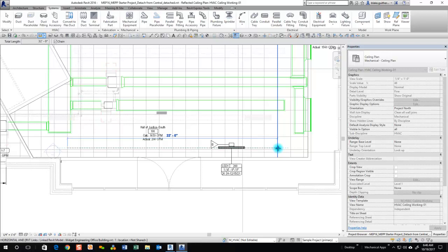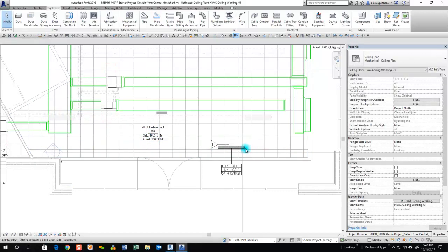I'm going to plan for providing two 4-foot gaps in my linear slot run, and the rest will all be designed based upon this airflow per length. So what that means is I have 32 feet. I'm going to subtract out 2 sections of 4 feet, which will just be blank offs. So that's 24 feet. And now we want 1660 CFM over 24 feet.